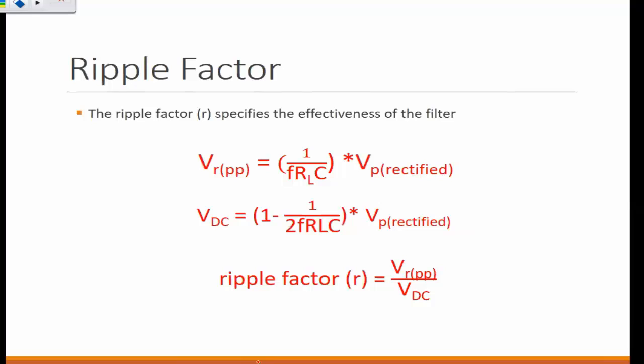All right, so now comes the fun part of how to use these formulas. Some of these are pretty straightforward, and for some you need to know how to use your calculator. But always remember: does the filter come after the rectifier or before the rectifier? So where is the capacitor, before the diode or after the diode? The filter stage comes after the rectifier stage.